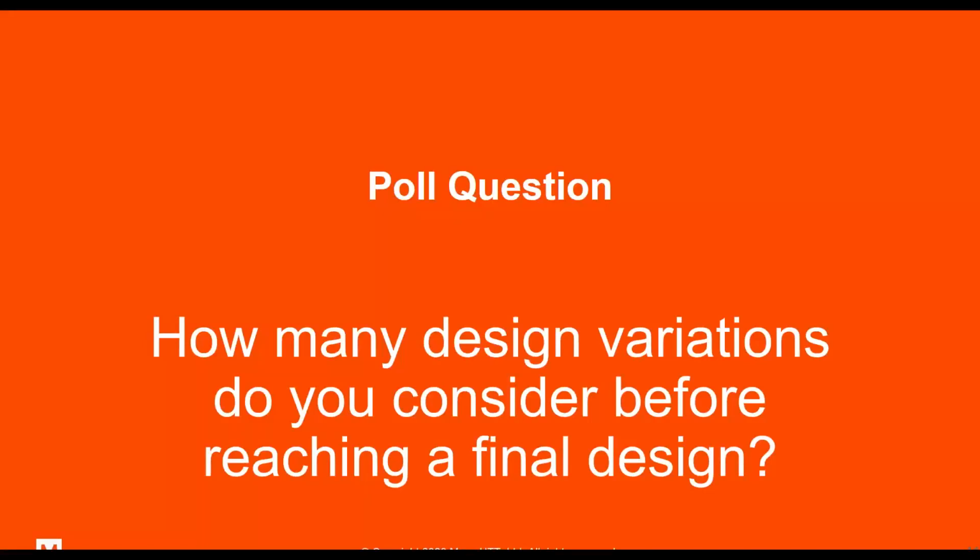That's the first one, the time limitation. The second one is when you build all your design variations and now you start solving those designs, there are some limitation again in time and also in licensing. So at the given location, at the given company, you might not have enough licenses to run all the designs at one time. So you're going to have to do them in series. And essentially, you have to babysit the simulation. You have to make sure that you're not running into any design errors and so on.